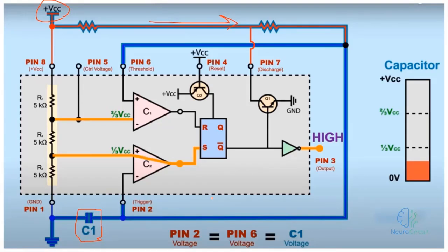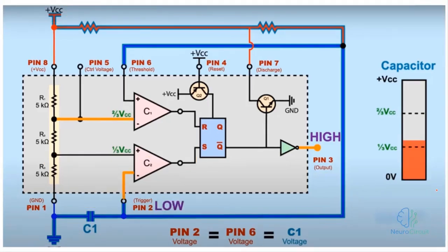Now, if you pay attention as we move to the right, the voltage across the capacitor is increasing. When the voltage of this capacitor exceeds 1/3 of the VCC voltage, it becomes charged. You might be wondering, well, at one point we said 2/3. Well, that capacitor was related to that part, to the time when it was connected to pin number 6. But here we have pin number 2, and with just 1/3 of the voltage, this capacitor gets charged for us. So in this case, when the capacitor reaches 1/3 of the voltage, comparator number 2 goes into the low state.